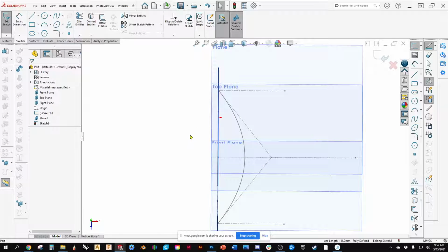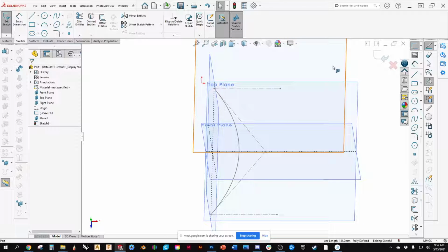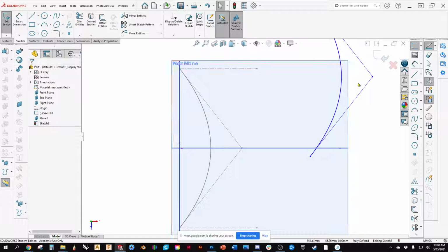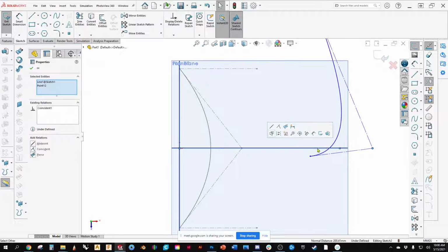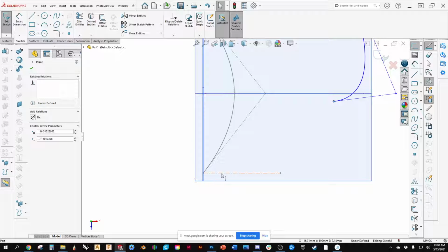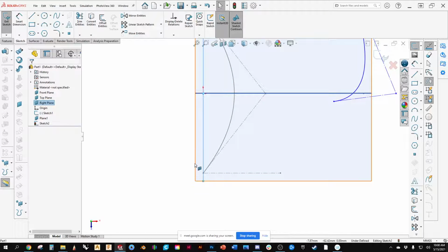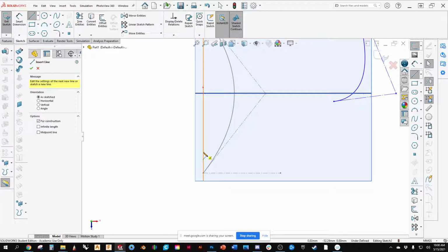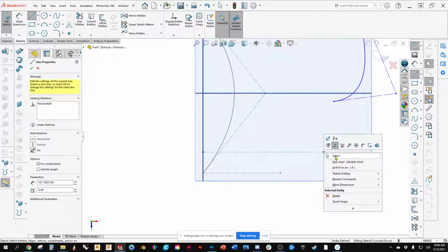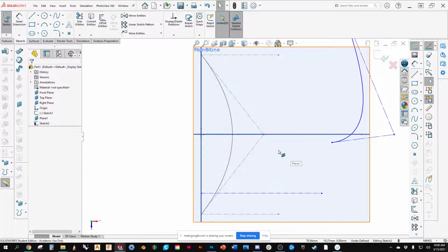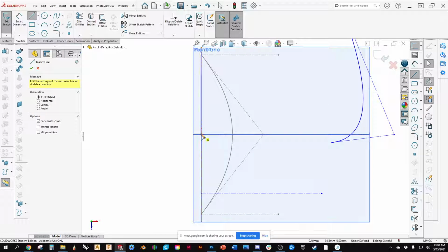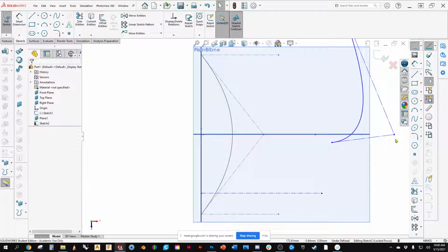So what you can do, by copying onto this sketch, is easily snap that to there. Now, I don't want to snap it to the point on here. So let me just come in. You can see how this is going to take me more time to set up than the swept surface, because with the swept surface, I'm doing 2 curves.